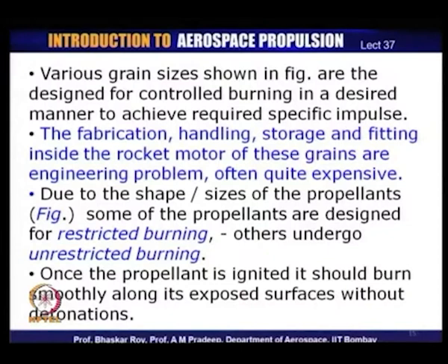Now, due to the shape and sizes of the propellants, some of the propellants are designed for what is known as restricted burning, and others undergo what is known as unrestricted burning. We shall see what these mean: some of the surfaces of the grains are restricted from burning, whereas in some other designs all the surfaces are open to burning. So, we shall have a look at these shapes in the next slide.